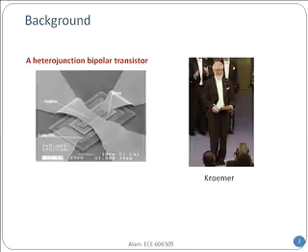The reason is, of course, that reducing capacitance is everything, because by removing the material from underneath, you are removing the line capacitance. Unless you remove the line capacitance at these high frequencies, before the signal comes to your device, most of it will bypass and return back to the source and will not reach and be amplified by this transistor.